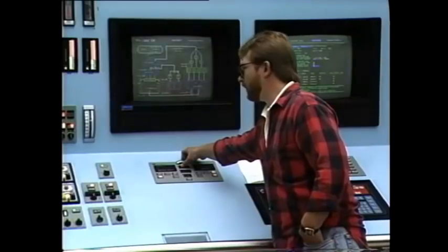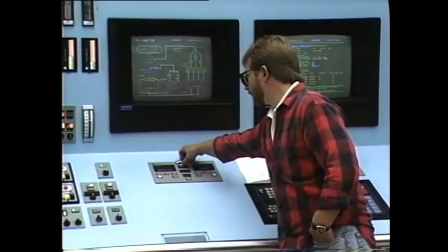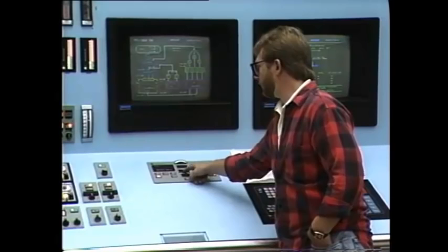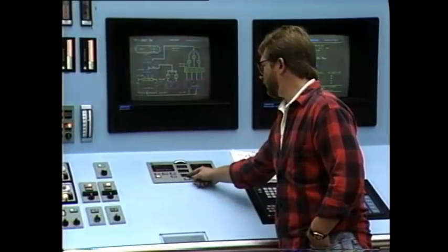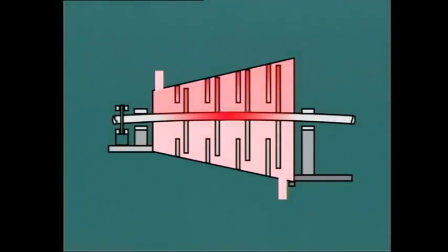In order to increase the output of the turbine, steam flow is increased, and this consequently adds more heat to the metallic components, causing expansion. The operator must take care not to increase steam flow or steam temperature too rapidly, as this could lead to unequal expansion of components and possible distortion. When this occurs on the rotor, it leads to an increase in eccentricity. The shaft and rotor take on a slight bow due to temperature distortion, and this is exaggerated by the centrifugal force of rotation.